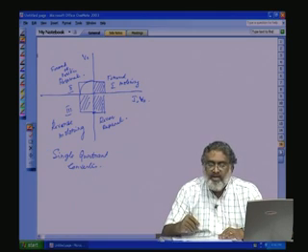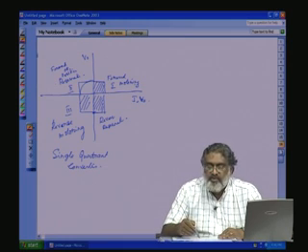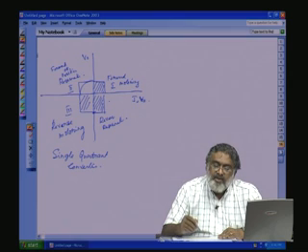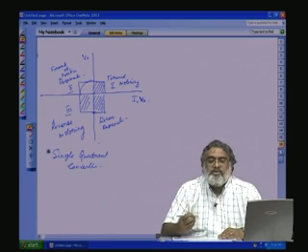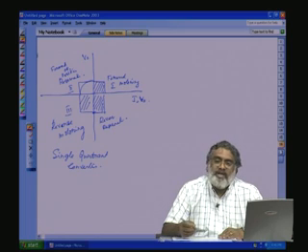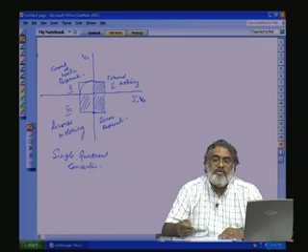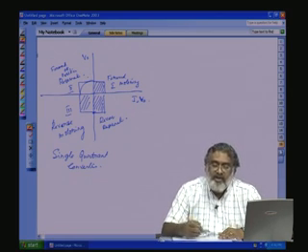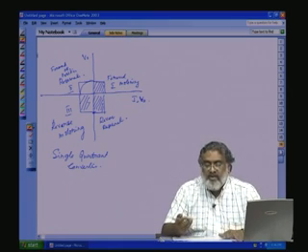Let us think about a converter where at least we can have forward regeneration. Forward motoring is possible, forward regeneration is possible, or reverse regeneration, where the voltage can go negative. So from the converter point of view, current can only go in one direction because of the thyristor and diode connection, or even if you use 4 thyristors instead of 2 diodes. But we can have a negative voltage, so at least we can have 2 quadrant operation out of the 4.